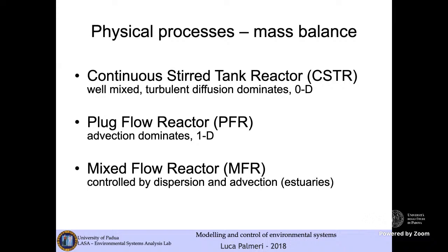We may generalize this approach by introducing a plug flow reactor, in which processes of advection dominate. In this case, we are one-dimensional, or we may employ an MFR, a mixed flow reactor, that is essentially controlled by dispersion and advection. And this is typically what you do when you want to describe estuaries or coastal zones or sea areas.